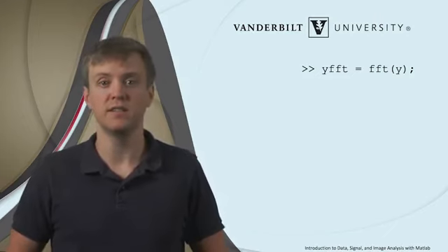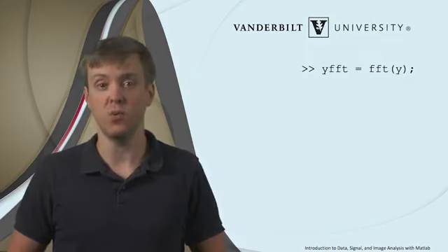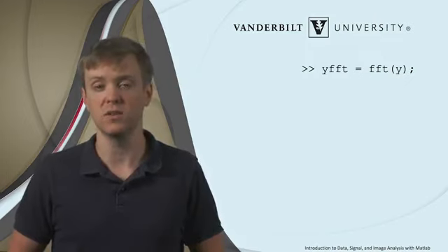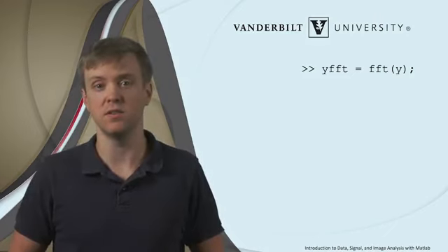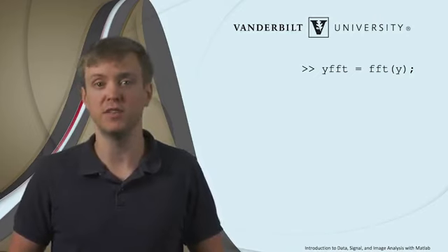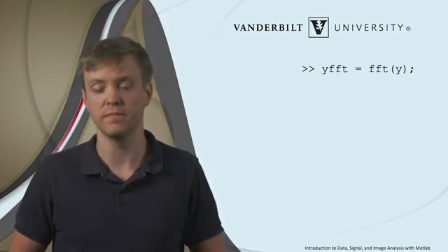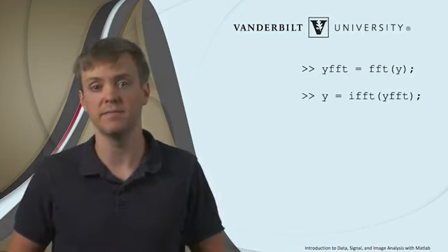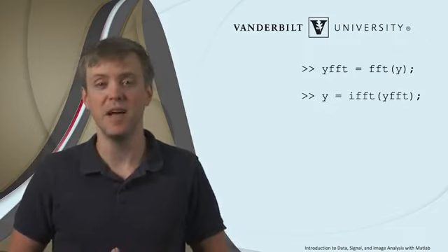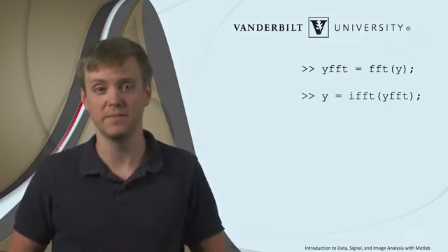This will not only let us easily see or quantify what frequencies exist in the signal, we can also very easily manipulate the frequency content of a signal in the frequency domain and then return the manipulated signal to the time domain form using the inverse Fourier transform, which is implemented as IFFT in MATLAB. Okay, let's go to MATLAB and see how this works.